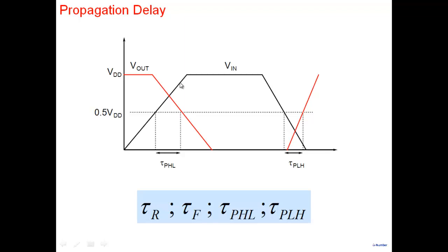Input is this black line here, right? And we are applying this input to the inverter here. So in response to this input, it's going from 0 to high and high to low. Let's say the output goes like this here. When the input is 0, the output is high, VDD, and then the input is switching, the output remains till perhaps the input reaches about the threshold voltage, then the transistor starts conducting and the output starts falling.